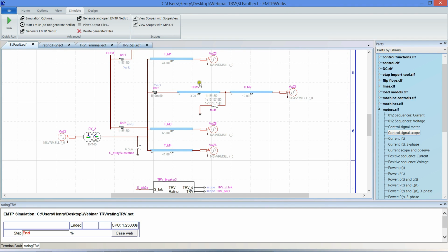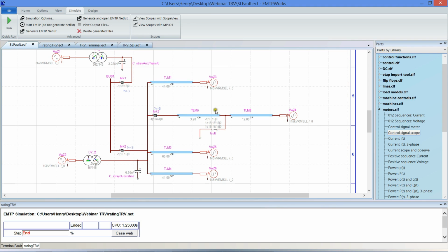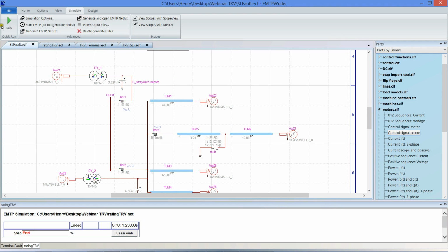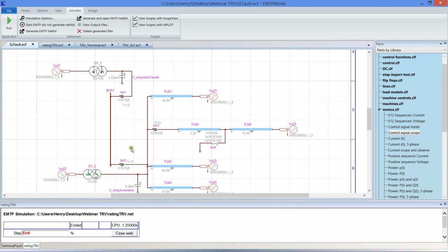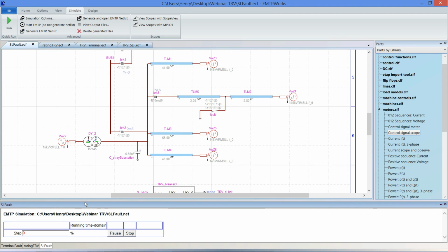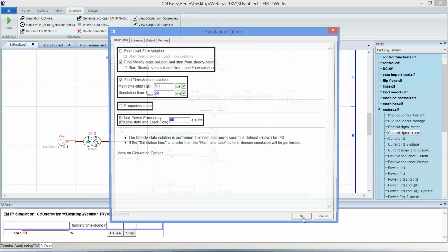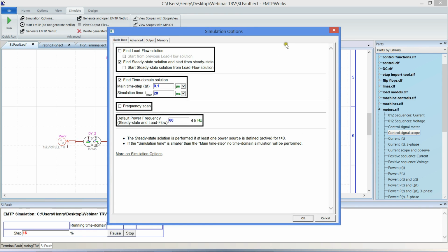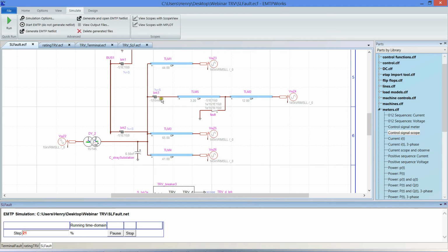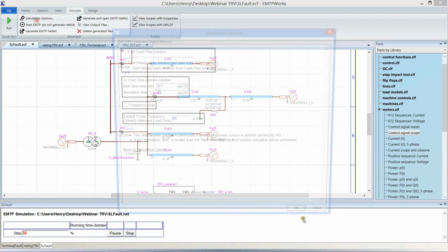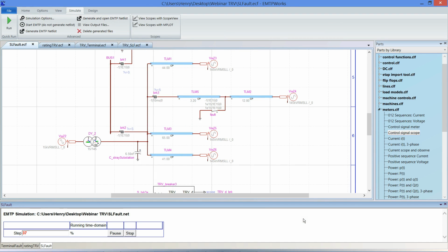After this case I will change the line and compare the result between CP and FD. But let's first run this one and look at the results. See the simulation now, it's way slower because it's an extremely small time step. We are talking here of 100 microseconds, right? But it's the time for the light to go through that, and it's this phenomenon of the short line that will make the rate of increase very bad.